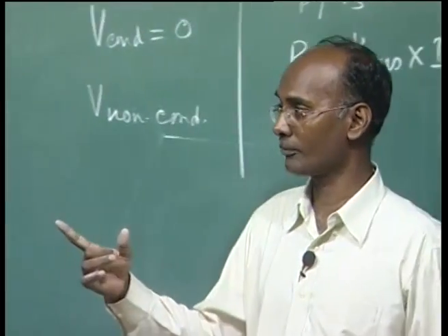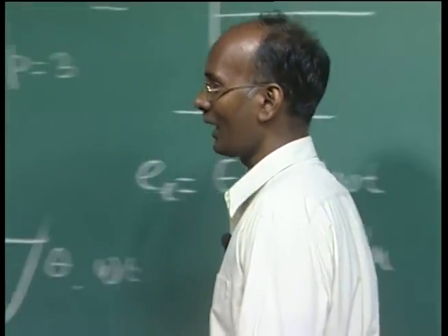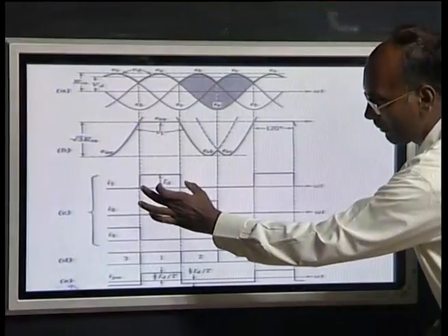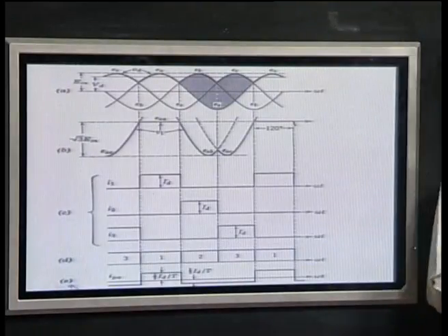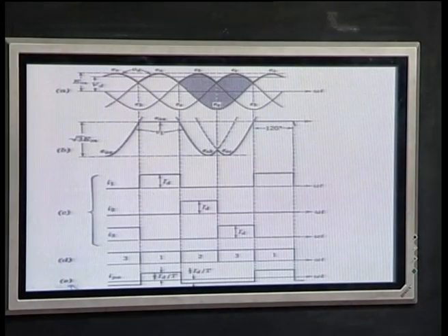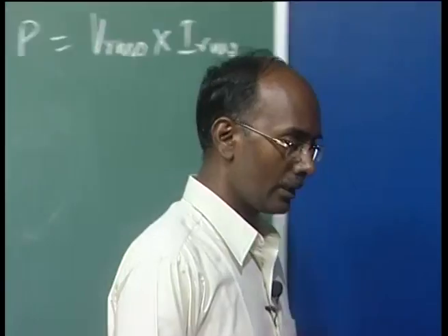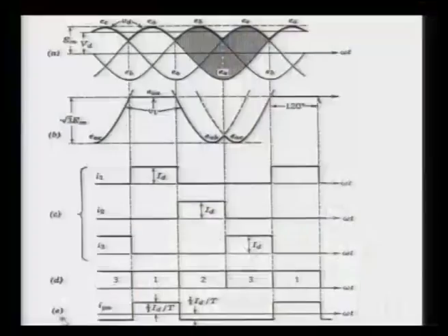And due to this, again our transformer is not utilized properly. In this case, the transformer primary winding is conducting for 120 degrees, and the remaining time this one phase is idle, and only 120 degrees this and 120 degrees this. So, the utilization of the transformer, if you analyze, is not proper. Also, it is giving some DC current that is appearing in your secondary side, and that is not desirable, because if you take the average of any of the phases in the secondary side, it is a DC, and the DC current is not desirable in the transformer.